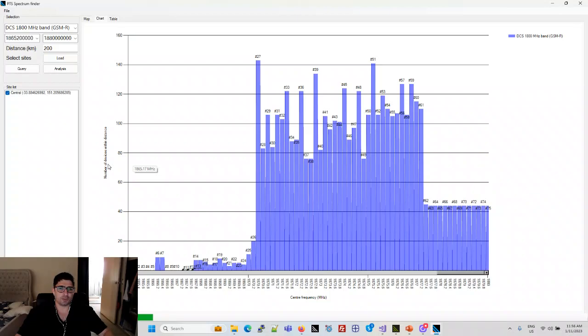Partially or completely. Normally, for the number of devices, I was thinking maybe you need to divide them by 2, but in fact no, you don't, because we only have the TX here. So what I understand is that channel numbers 1, 2, 3, 4, 5 are not used at all. I can also understand that 8, 9, 10, 11, 12, maybe 13 as well, yeah, 13, are not used. And I can see the lower part of the spectrum, which is 14 to 26, is underused. They are used less than maybe 5 times or 10 times. That's the reuse in the whole network.